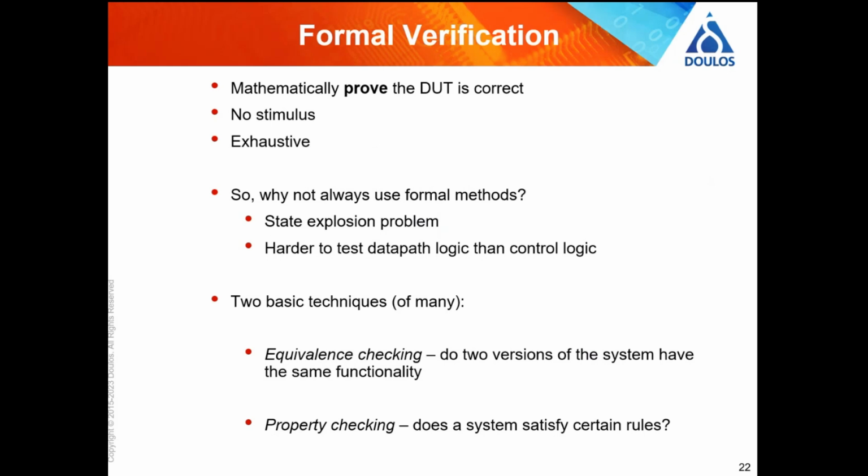So formal verification, I've just been talking about this really very quickly. So really cool. You don't need to write the stimulus. You might need to write some rules, however. So we're going to talk very quickly about two kinds of formal. One is property checking, where you write the rules, and the other is equivalence checking, where you compare your design with another design, basically. So the rules are probably written in a language called SVA, and we'll see an example in a minute. That is SystemVerilog assertions.